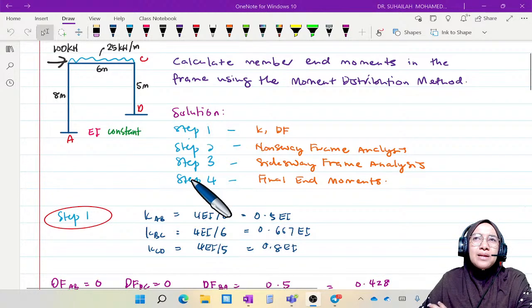And then we have to calculate distribution. We have to assume F, and then do the distribution process. Repeat the same process again, the same as the 2A process, except the FEM value is different. Then we get M prime from the table, and then by using the end moment M prime value in table number 2, we will calculate the R prime value.